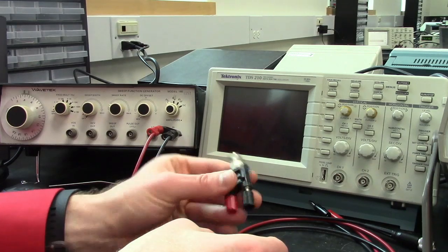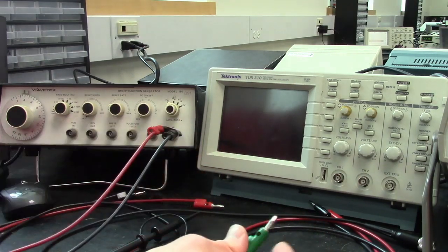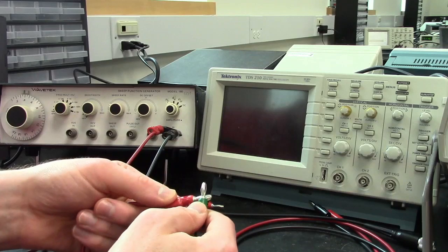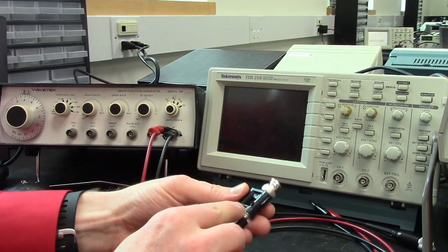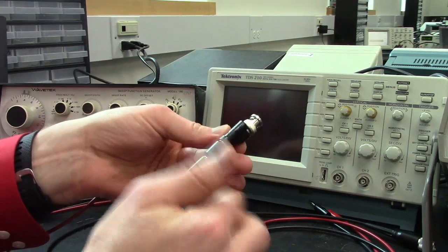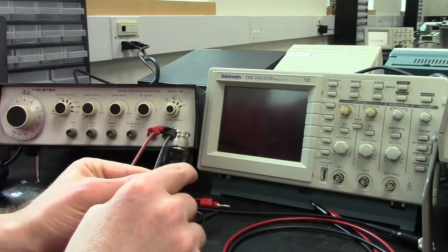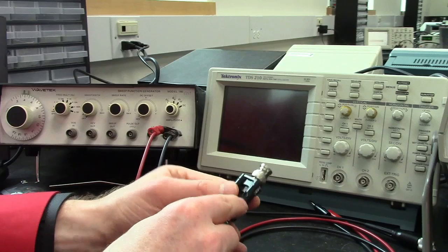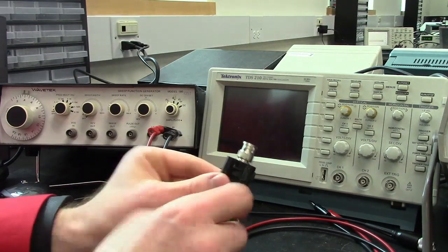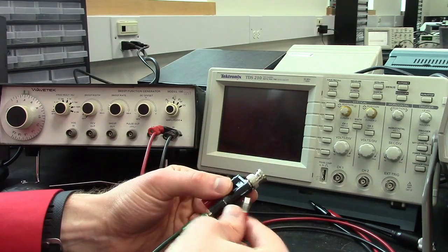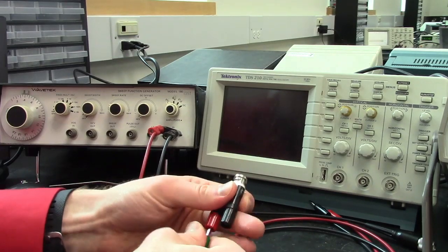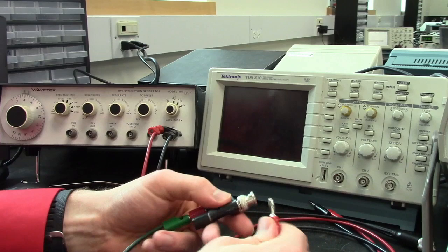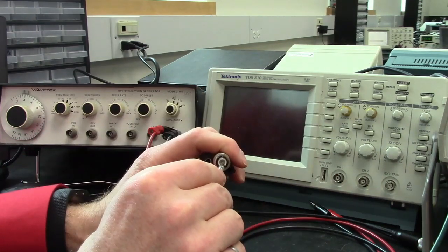To see what's connected to what, you can use the multimeter that is connected to these in short detection. So we'll check first of all the negative terminal of this, indicated by the black symbol here, and also by the little negative sign on the output. And this is actually connected to the outside of the cable. In contrast, the positive is insulated from the outside, but is connected to this tab on the inside.